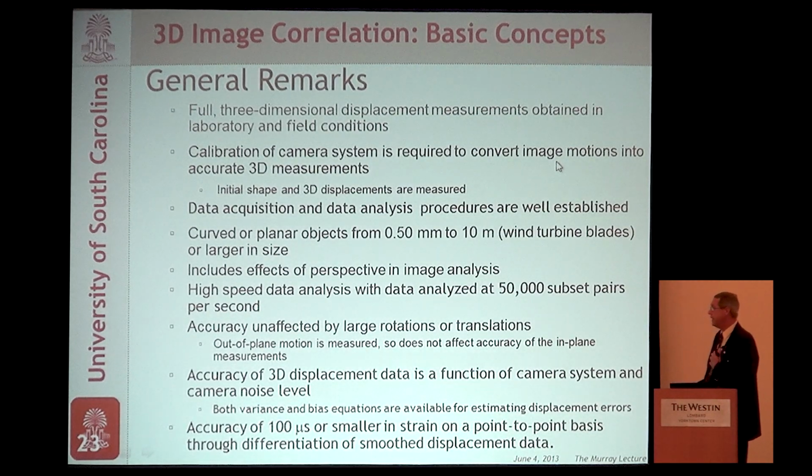Well, this one, 3D DIC is probably the standard today in many cases. Full three-dimensional displacement measurements are obtained in both laboratory and fields. I've personally used it in the field on several occasions, including tanks, large water tanks, and other cases similar to that, just to measure deformations during the filling and the draining of water tanks. You can calibrate this thing fairly simply now to get the parameters you need to actually convert the images into 3D displacements. The data acquisition procedures are well established. You can do curved objects and large objects up to 10 meters, and small objects on the order of a few millimeters or smaller today.